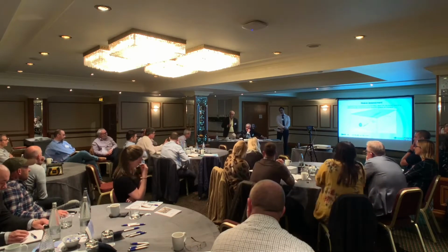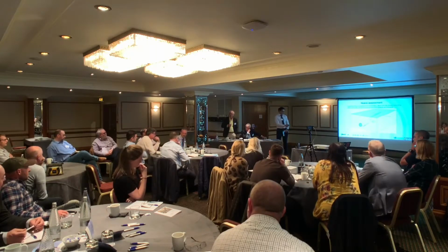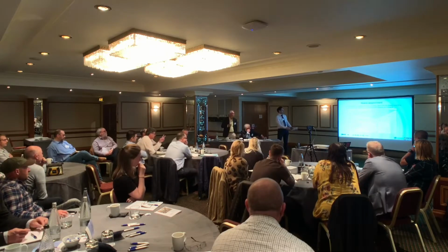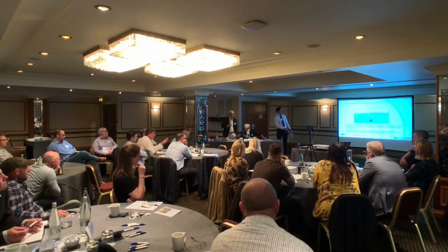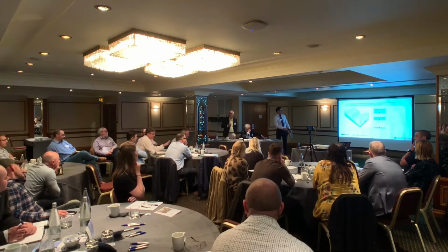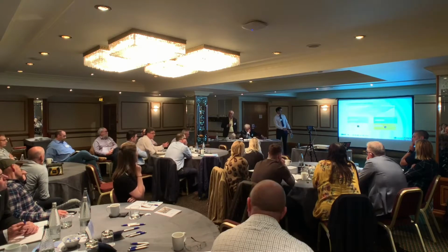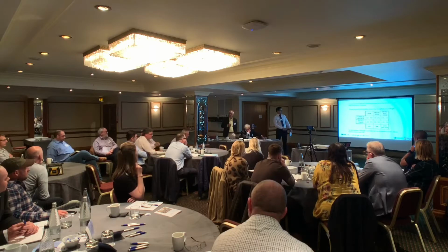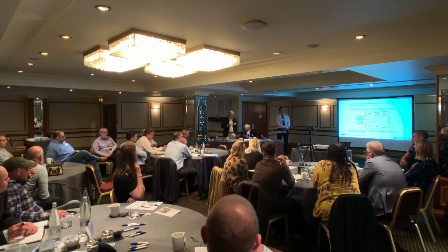Could you put the percentages up? The face wash. Well, there's two things. The soil does not fall into the tunneling machine. I will tell you right here and now, the ground squeezes into the tunneling machine because it has no option. When you remove soil in front of the tunneling machine, the ground above squeezes the soil in towards the tunneling machine. Tunneling machines, by and large, have a face pressure either from slurry or earth pressure balance to counteract it.